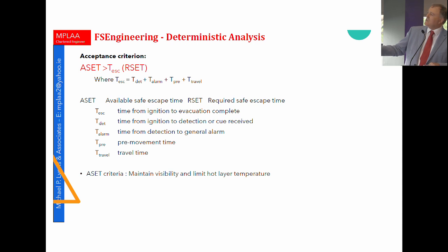So you've got to consider the time to evacuation. And the time to evacuation includes everything from the time from ignition to detection to alarm, pre-movement time. Irish people have a long pre-movement time. North Americans move very quickly. We have to wait for the smoke to be burning underneath our feet. Say, oh yeah, there's a fire in the building, I suppose I should go. And then the travel time. And we'll all vary on our travel time from the point where we're occupying to where we are outside at the assembly point, or at least out when we go to the final exit, as we step out into the open air where we expect it to be safe.